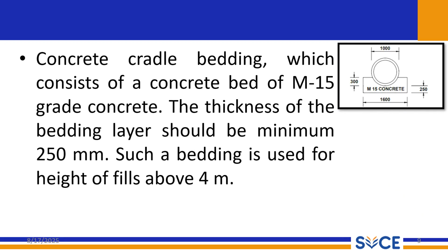Then the concrete cradle bedding, which consists of M15 grade of concrete. The thickness of the bedding should be minimum 250 mm. Such bedding is mainly used for the height of fill above 4 meters.